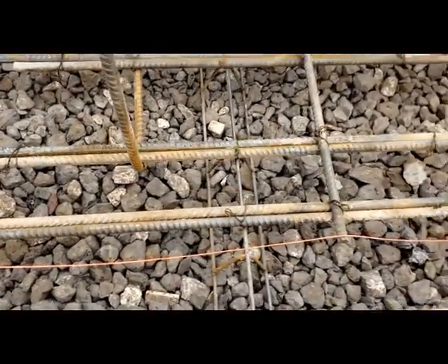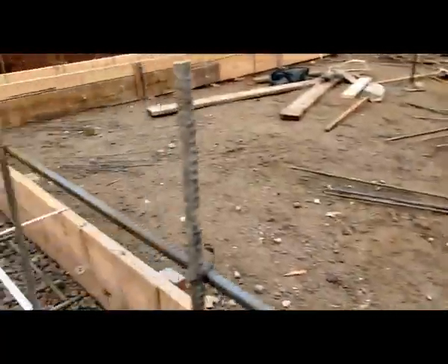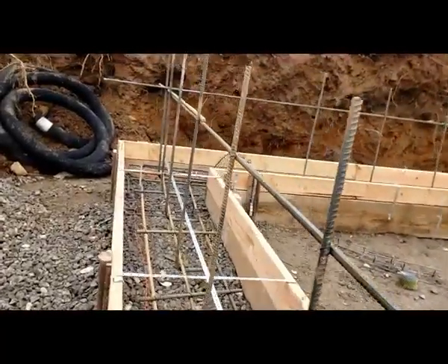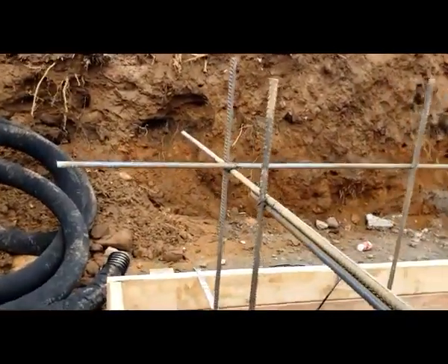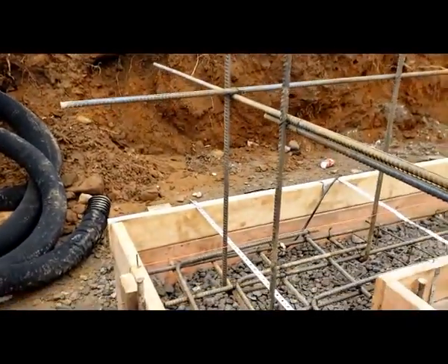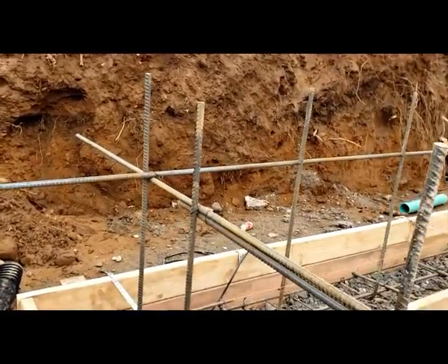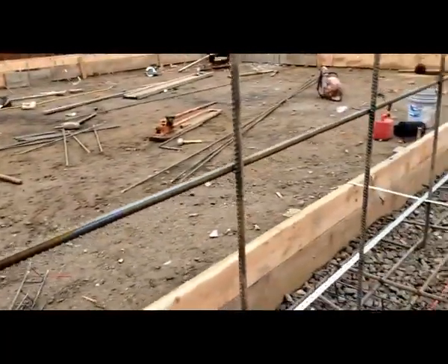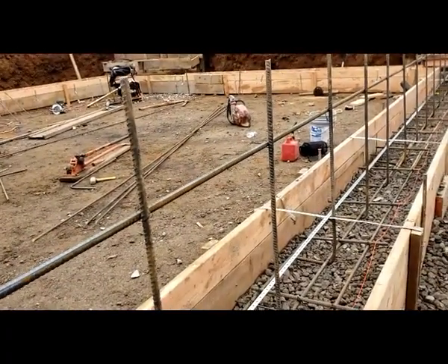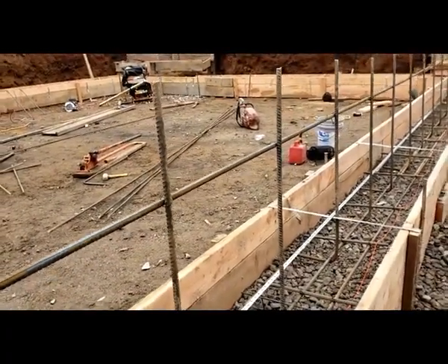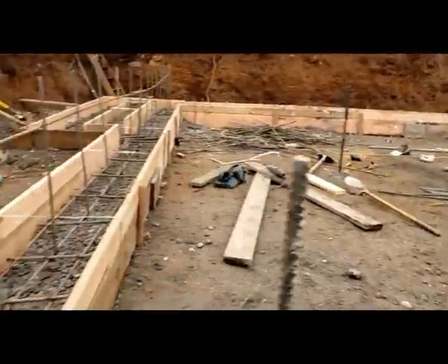So make sure you go over the overlaps, all right. And we have verticals, and this is tied to the wall every 2 feet as well. Read the plans. Not all the plans are the same, so go over the plans with your contractor. Make sure he gets this right. Those verticals are very important because this is how you're gonna tie the wall to the footing. Some people do it this way, other people would stick it while the concrete is still not hard.